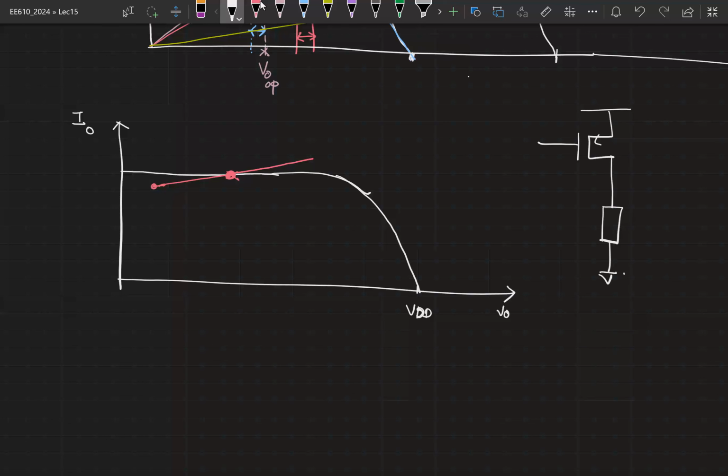So we said that we have identified some point through which it needs to pass, and it needs to have a smaller slope, and if it needs to be a passive device, then at some point it has to come down like this. Okay? So does this red curve remind you of something? Transconductance of a MOSFET, but we are looking at an I0 versus V0 curve. Does this remind you of some IV characteristics of some device? A transistor with channel length modulation, right? In particular, what transistor should this be? It has to be an NMOS transistor, right?